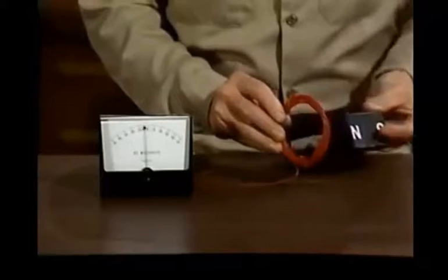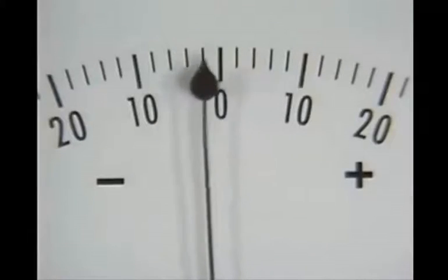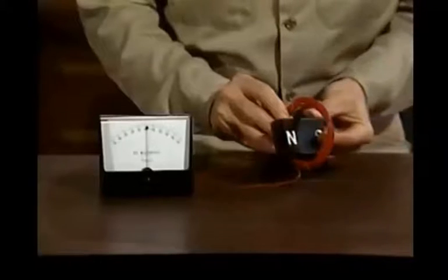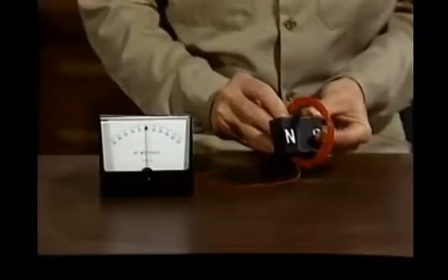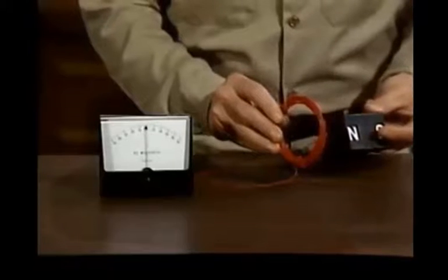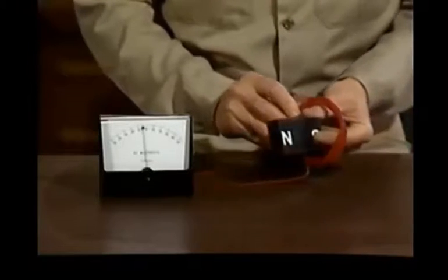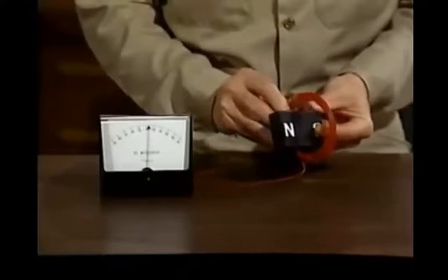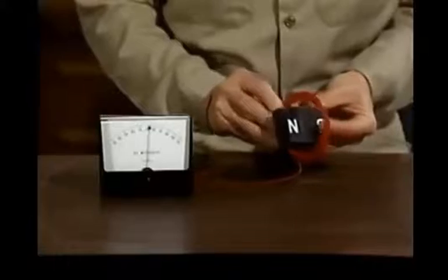Notice that as the magnet moves through the coil, the indicator swings alternately between positive and negative. If the motion stops, the indicator moves back to zero. The same thing will happen if the magnet is held stationary and the coil is moved around it. That's what relative motion means. Either the conductor or the magnetic field has to move. The electrical potential that's created in this situation is usually referred to as an induced electrical potential. The conductor, the magnetic field, and the relative motion induce an electrical potential in the conductor. This is the basic principle behind the generation of electricity that's used to operate equipment in industrial facilities.